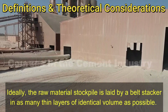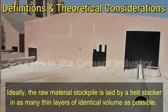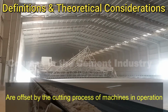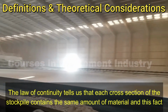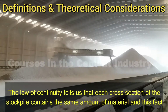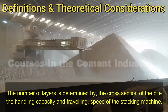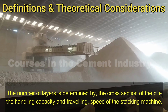Ideally, the raw material stockpile is laid by a belt stacker, in as many thin layers of identical volume as possible. As a result of this large number of layers, varying material properties in superposed layers are offset by the cutting process of machines in operation. The law of continuity tells us that each cross-section of the stockpile contains the same amount of material, and this fact is the essential prerequisite for a good homogenization effect. The number of layers is determined by the cross-section of the pile, the handling capacity and traveling speed of the stacking machine.